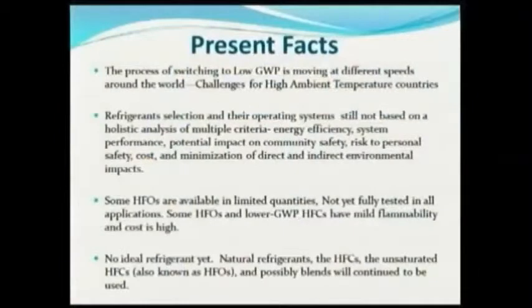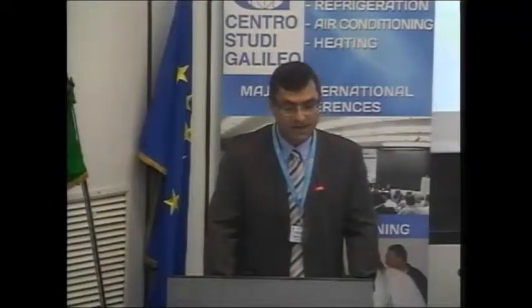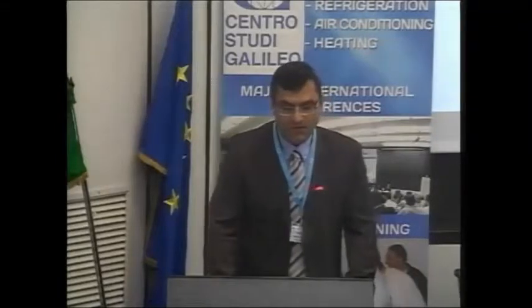Also, GWP phase down is happening at different speeds around the globe. We have some issues in high ambient temperature, and refrigerant selection and the design of operating systems are still not based on holistic analysis of multiple criteria: energy efficiency, system performance, potential impact on community, safety, risk. We have a lot of cost, of course, and need to minimize the direct and indirect effects. We have a lot of issues to discuss here when we speak about a holistic approach. It's not fair really to speak about only one aspect when we speak about refrigerants.